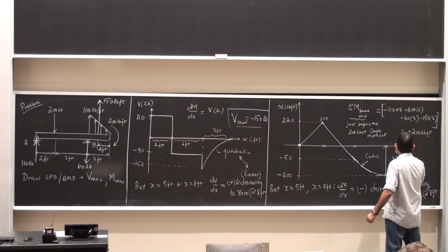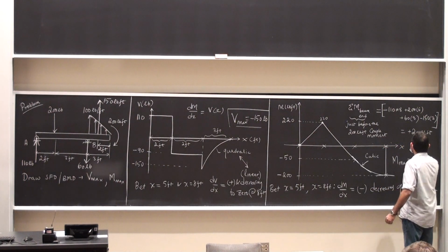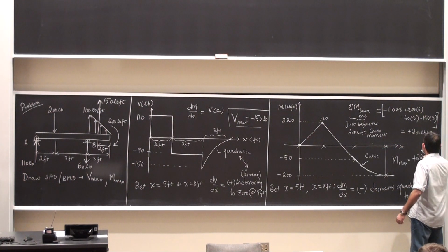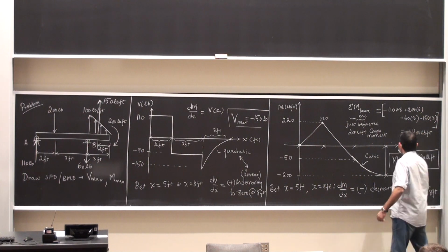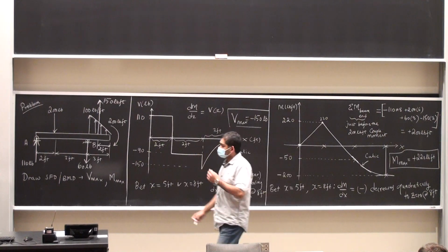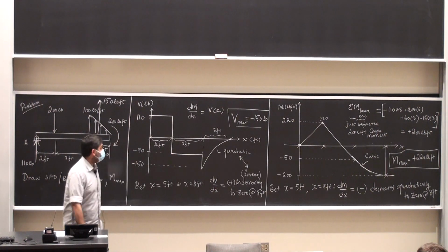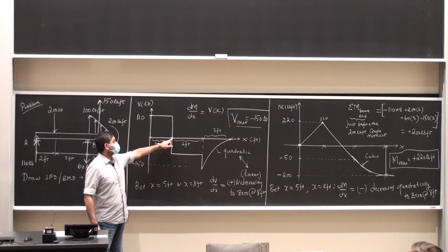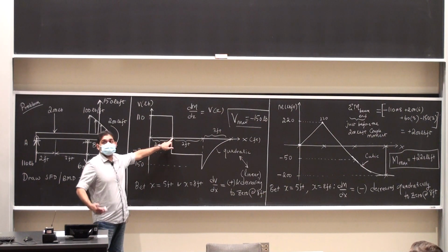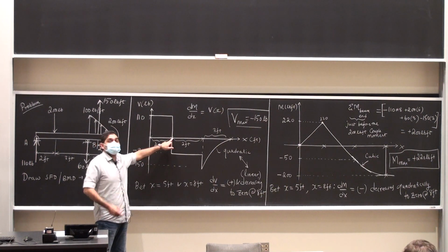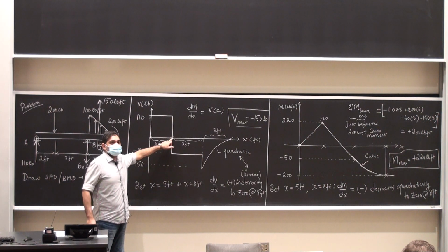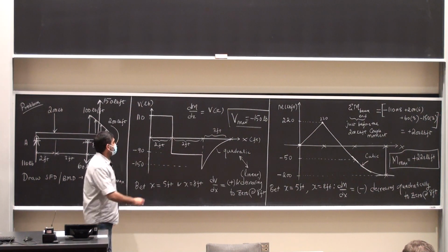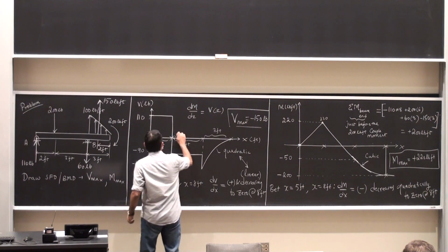The value of the largest bending moment is 220 pound-feet positive. And M max is plus. Which makes absolute sense, because this is the point of zero crossing for the shear force diagram. So the maximum bending moment value has to occur at that particular point. Isn't that what it is? Right? So this is the point of zero crossing.